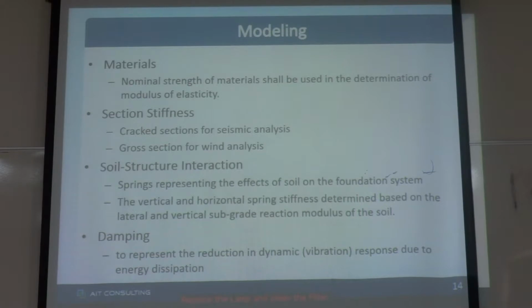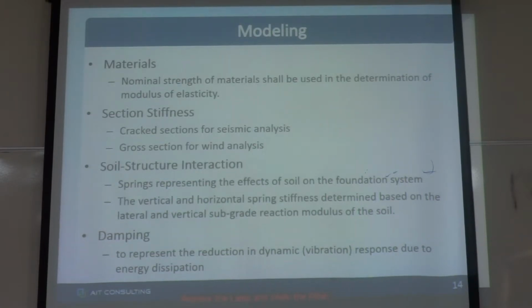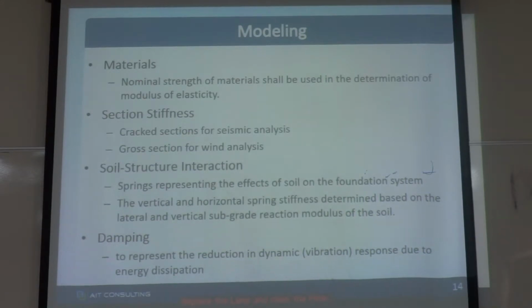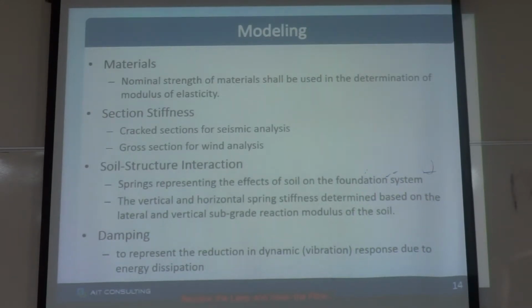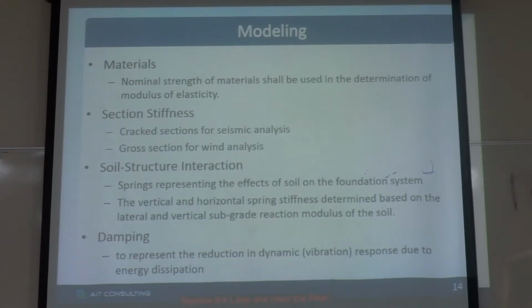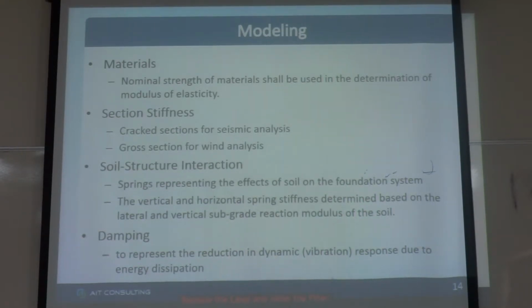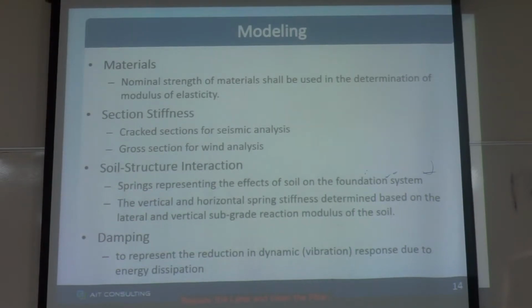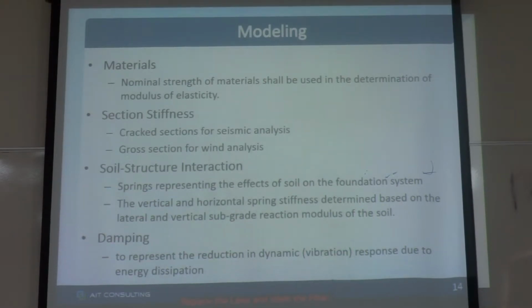This is the modeling stage. In the modeling stage, we have to model the materials and member sections, as well as the boundary conditions. If you are considering soil structure interaction, or if you do the design for seismic loading, you have to consider the damping.